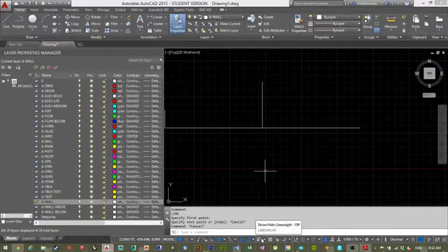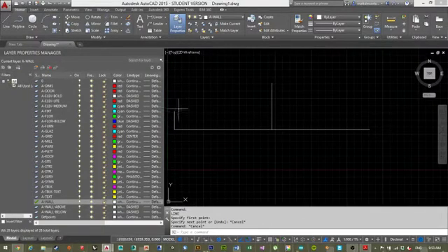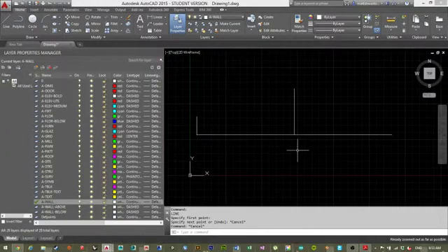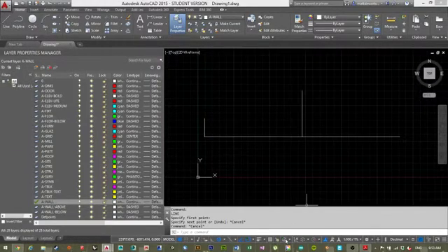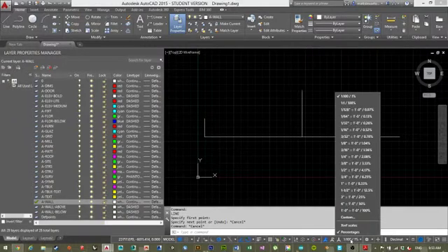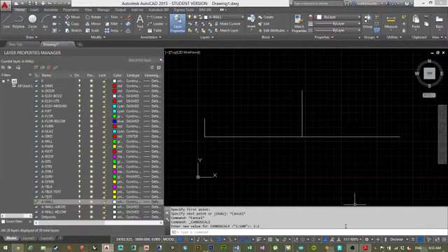So the other ones in here, let's see, if you've actually put line weights into your drawing, which I don't do, you can turn it on or off here. You can turn your transparencies on or off. And a bunch of these other ones are dealing with 3D. I did 3D in AutoCAD once, but I would not suggest it. Do that in Rhino. And then over here are your scale and your annotative objects.